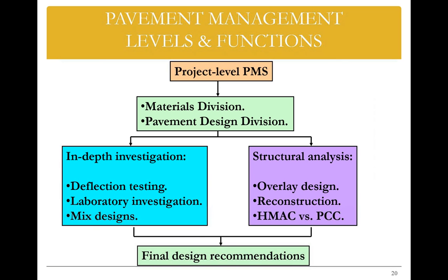Meanwhile, you would also be required to do structural analysis to decide if you are going to come up with an overlay design or a major reconstruction. Also, when you are looking into a project level PMS, you have to think of the two options that you have available, which are either hot mix asphalt or Portland cement concrete, which eventually is going to come up with a final design recommendation to fix the issue.